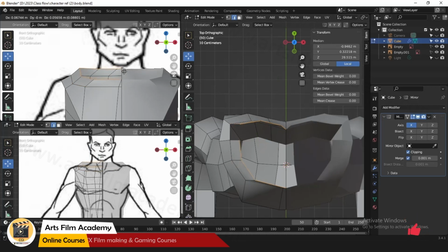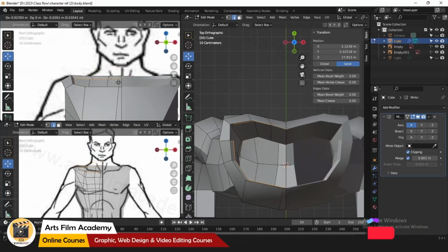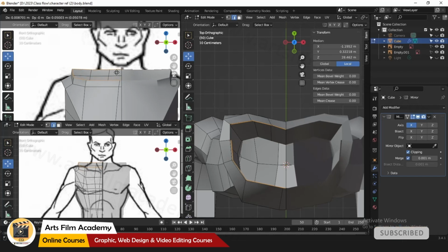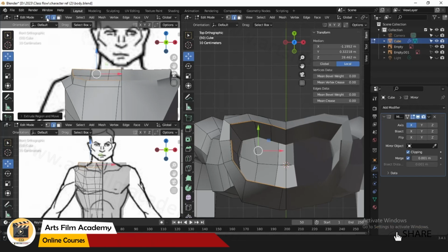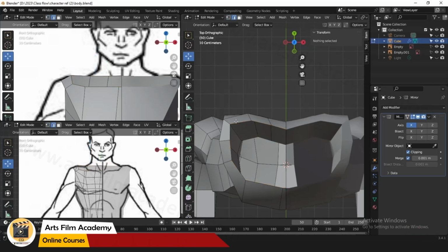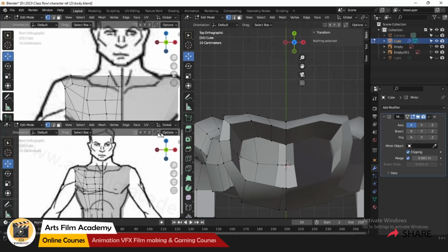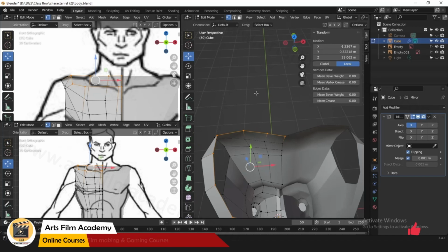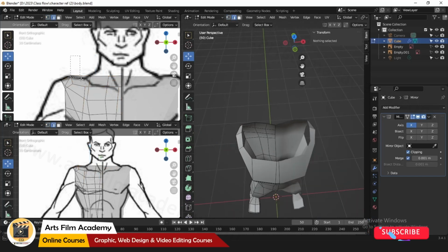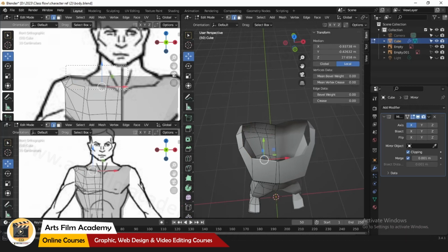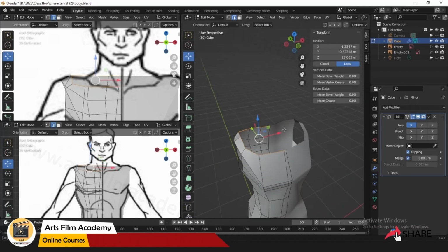E extrude, bring it closer, but when you're doing, see the center is snapping, so just keep it here. Later on go to the vertex mode, deselect this vertex and bring only the required inside closer. Okay, again make sure you are in the X-ray mode to select the segment. If you are not in the X-ray mode, we may miss some of the segment. Okay, so make sure you are in the X-ray mode, drag like this. Okay, in the edge mode, drag it like this and see whether you have selected the upper edges perfectly.